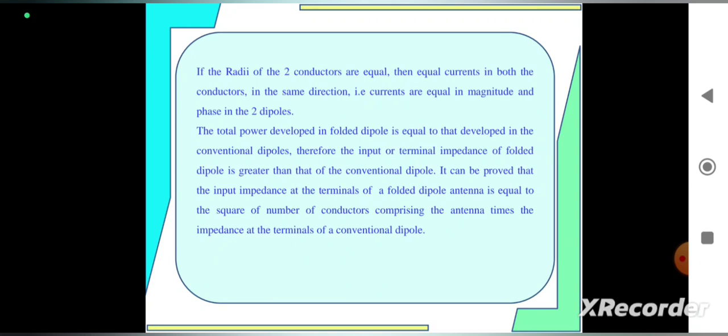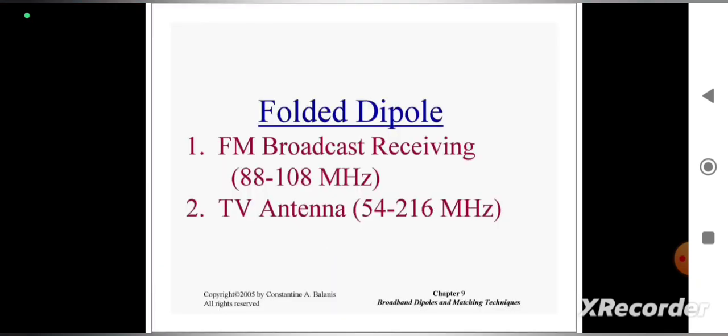Therefore, a three-wire folded dipole or folded tripole can be fed with a conventional 600 ohm two-wire open transmission line without any matching device. So, the folded dipole antenna or tripole antenna has an important impedance transforming property. This makes it easy to match with a transmission line that feeds the antenna.